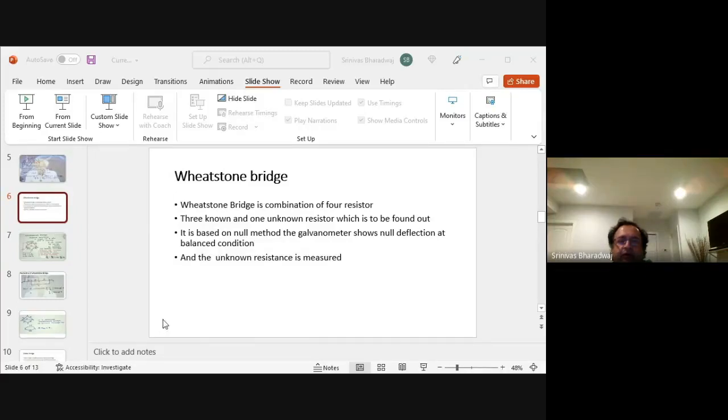Okay, so I equals V divided by R1 plus RV plus R prime. Therefore, you end up with this whole equation. So when you have that phi, and then a proportionately reduced phi, it exactly matches the voltage of E. Okay, and so that's the idea there with respect to how to find the internal resistance.